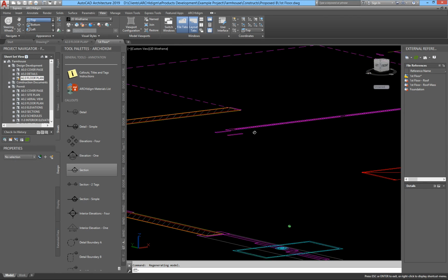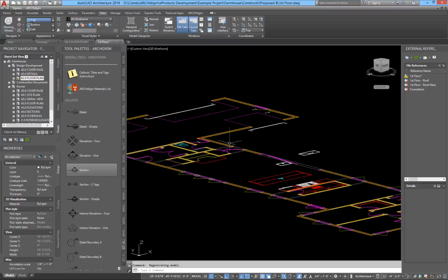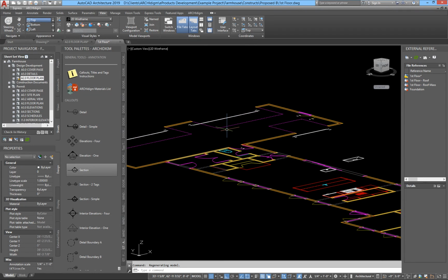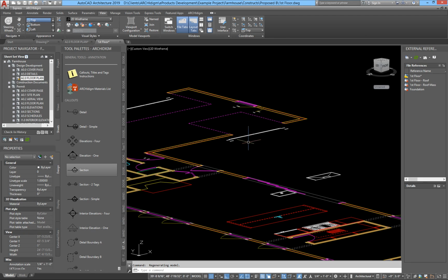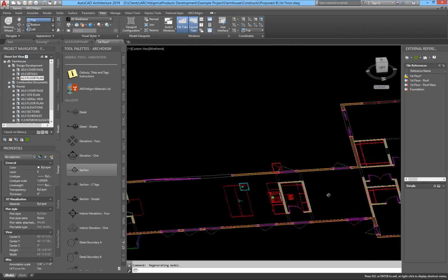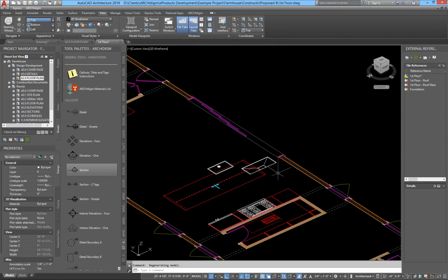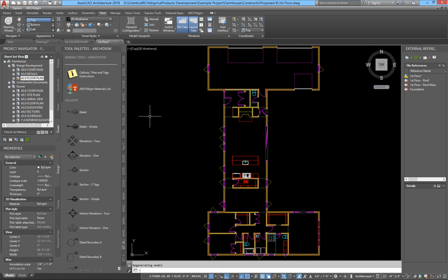You can see on these garage doors, they're sitting lower when I go down, and that is because the floor slab of the garage was, in this particular example, I think maybe 8 inches or so lower. So it thinks that that's the 0 plane because the object is residing at that plane. Likewise, the hood is sitting up high because that's where it was placed in terms of Z. And so the end user receiving this stuff might have to do some cleanup work if they want everything flat. So I'm going to go back to World.